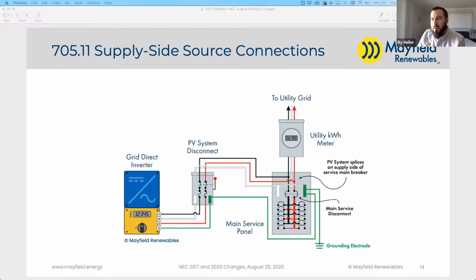And so I was thinking, well, you could put that in right near the inverter in either a gutter or wire trough, and then the wire from the PV output or the PV source circuit could be number 10 into that, but then you could have a short whip of number 8 on the output side of the fuse going up into the inverter. And so that could maybe solve that issue and keep that a viable option if there is an issue with the AHJ.